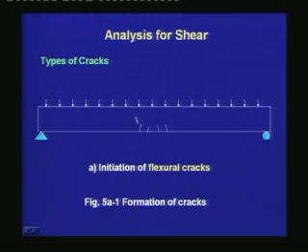Since the moment is maximum near the middle and the flexural stress is tensile and maximum at the bottom, the cracks generate from the bottom surface, and these cracks are called flexural cracks because they have generated due to the maximum value of the moment.